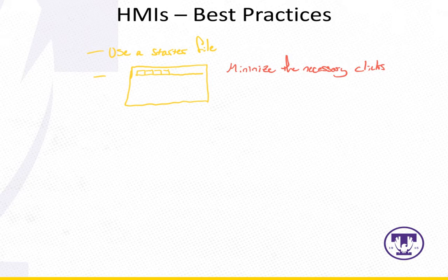It's much better to take a modern UI approach, so user interface approach. So when you're designing these HMI applications, what you should be thinking about and what you should be using as sort of inspiration is things you see in the Android and Apple interface. So they have perfected, at least so far as the industry has developed, user interface design. And Windows is coming up in the world as well, in my opinion. But Android and Apple have always been at the cutting edge of developing usable and functional interfaces. So emulate what you see on your phone. The design and layout of the page structure, the design and layout of the navigation structure. That's what you should be seeking to emulate when you create an HMI application.